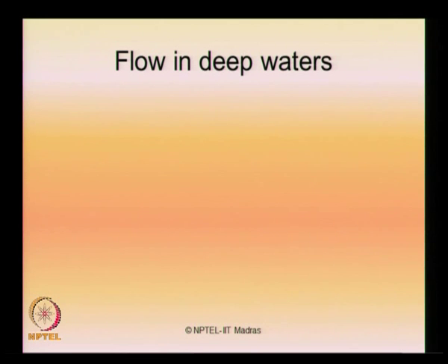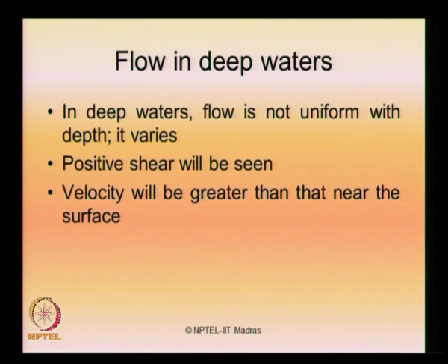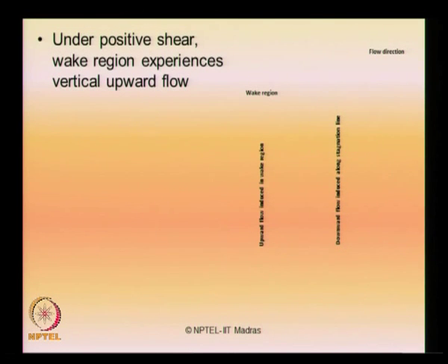Let us now understand the FSI in terms of deep waters. Of course, as we understand from the literature, in deep waters the flow is not uniform with depth, it varies with depth. There is a positive shear seen in this kind of behavior. The velocity of course will be greater than near the surface as you move. When the vertical cylinder is in shear flow condition, then you can always envisage that a 3-dimensional flow regime will occur.